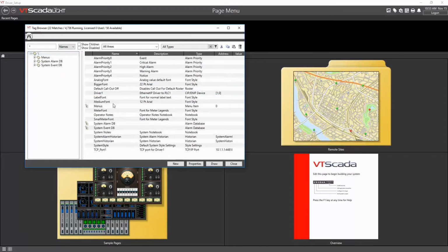And there we've created our driver for our PLC system. Now you'll see it shows up here in the grand list of all of our tags because it's part of the system tags now. But what we want to do with this is create tags: analog status, analog control, digital status, digital control, based around that driver. We want to link these two together.